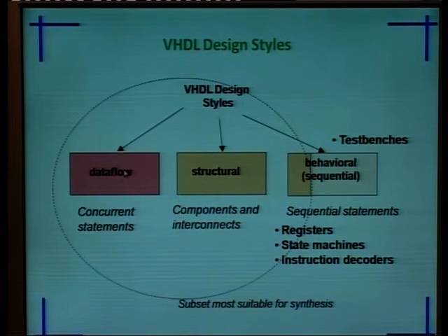But the main drawback of data flow is that we have to simplify the Boolean expression first. If we have a small Boolean expression, that is okay. But if we have a large number of inputs, then we have to go for the behavioral type of modeling. In behavioral, we write the truth table for our adder, implement the truth table in VHDL, and then simulate and synthesize it.